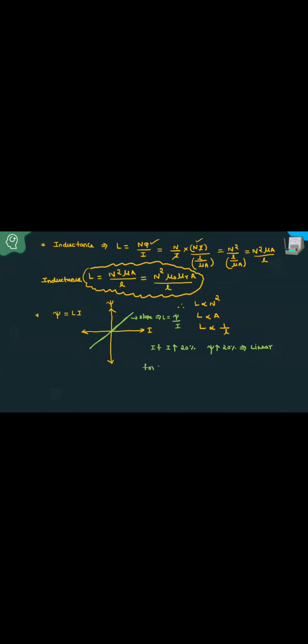For non-linear, what do you mean by non-linear? If I is increased by 20%, then what about psi? Psi is increased by only 10%. There is no proportional increase. Then L depends on I and psi, so L is not constant. If L is not constant, then it is non-linear.